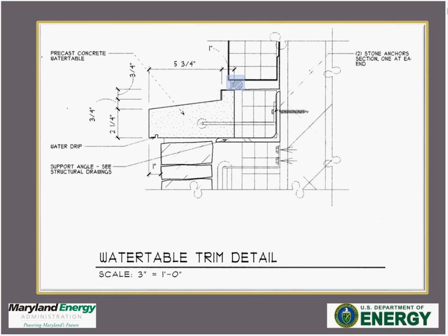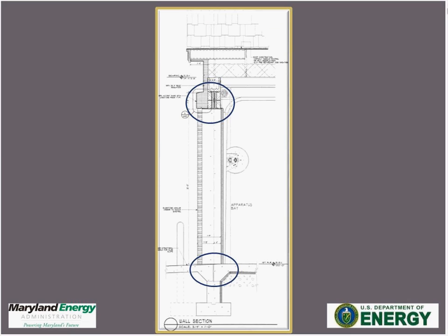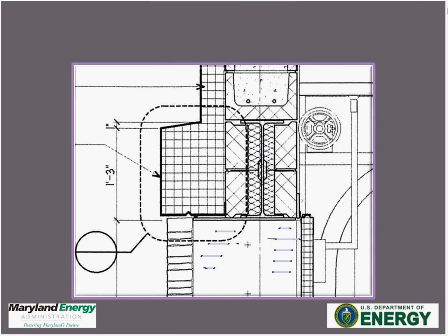We do see at the break between the exterior insulation finish system that backer rod and sealant are being used to maintain a continuous air barrier. This is only shown here graphically and should be called out via notes as well. Here we're showing a great deal of graphic detail, and again lacking in specifying notations. There's a section through an overhead door, steel header, and protected slab-on-grade construction. Let's look at the highlighted header junction in more detail.